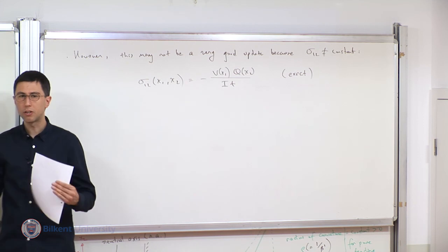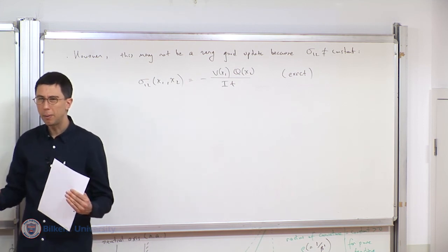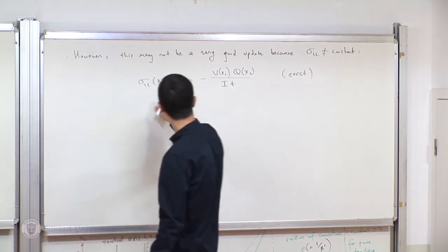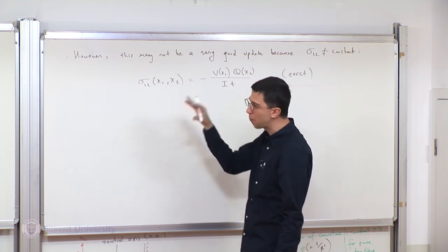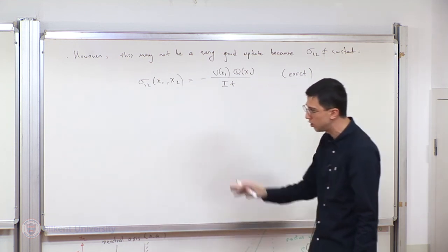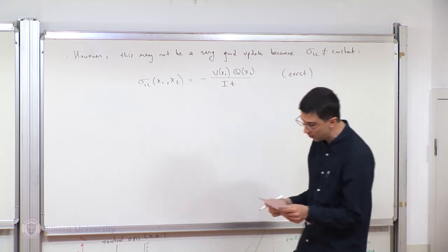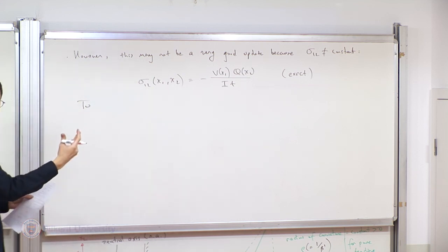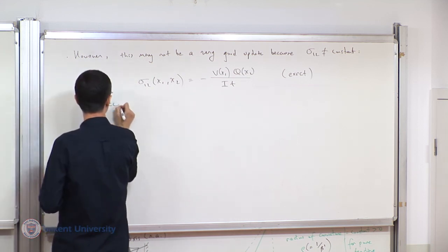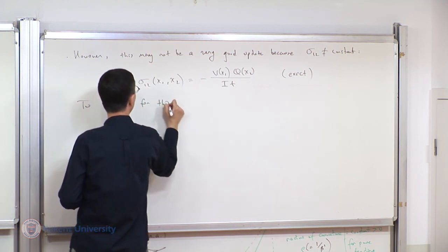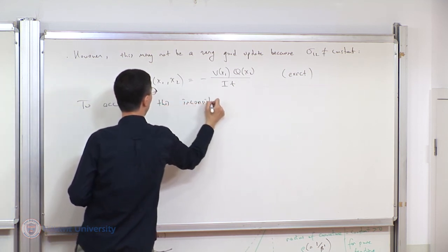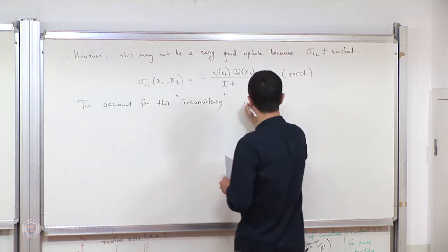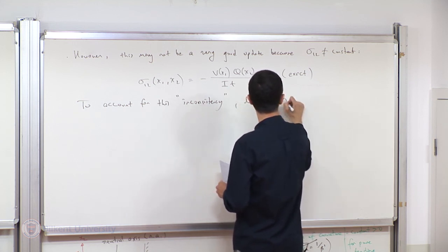So I don't want to sacrifice plane sections remaining plane, but I want to somehow account for the fact that I messed up here. It's not really a constant. It should have been varying. But I don't want to incorporate a lot more complicated approach into those statements. I want to preserve it, and I want to somehow account for this inconsistency in a very simple way and hope that it works. So to account for this inconsistency, referring to the fact that we have assumed the shear stress to be a constant, but it's not, I'm going to hope, right?